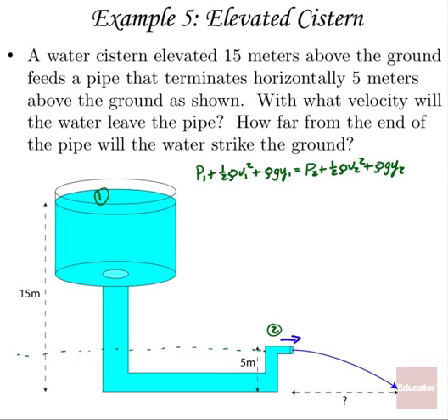All right, as we look at that, some simplifications we can make. P1 is open to atmosphere. P2 is open to atmosphere. They'll have the same pressure. We can subtract those out of both sides. V1 is going to be roughly 0. We can make that go away. On the right-hand side, if we're calling this the 0 height level for the first part of our problem, that term goes away. So we've simplified Bernoulli's equation to say that rho GY1 equals 1/2 rho V2 squared.